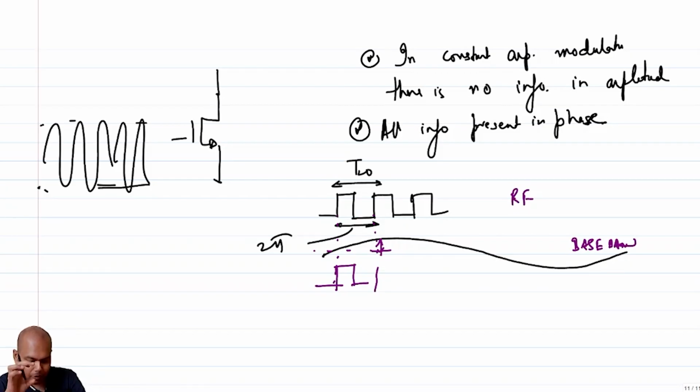I have the peak of the baseband signal, which means the rising edge will move by a large amount, right? So the rising edge of the RF signal, which was supposed to be here, will move maybe somewhere here. Then again here I have some heavy amplitude but slightly lower than what we had, so instead of moving here, it will move here, and so on, right?